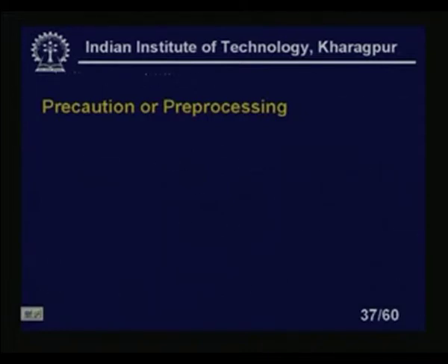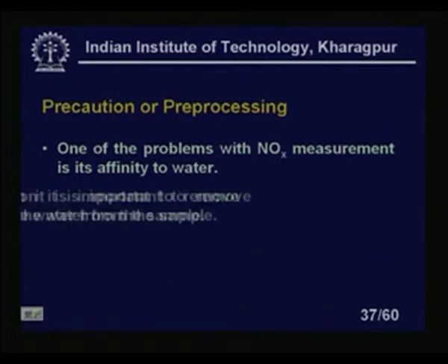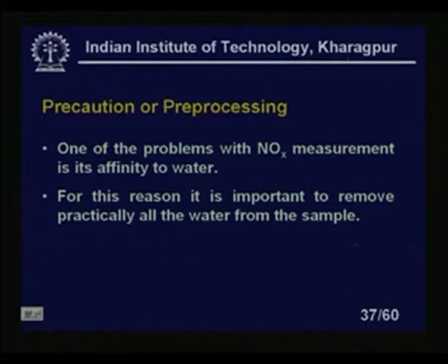Now, what are the precautions and pre-processing that we must note? One of the problems with NOx measurement is its affinity to water. Any water will immediately absorb it and you cannot find the NOx. So the container should be totally air and water free, that is the most important thing. For this reason, it is important to remove practically all the water from the sample before analyzing it.